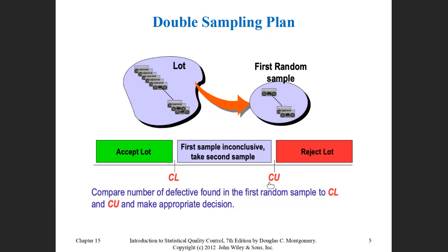If it exceeds the upper cutoff, as in the example, let's say 3 defective out of 5 in the sample size, that means it is rejected. So the cutoff upper will be 3. And the lower can be 0, or you don't have to define it, because usually they go with the upper limit in this case.